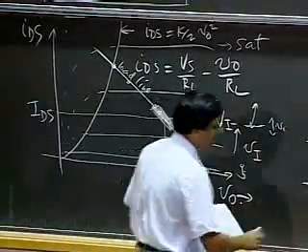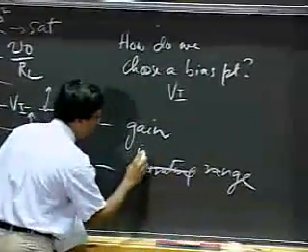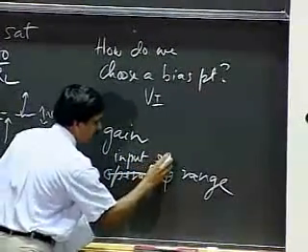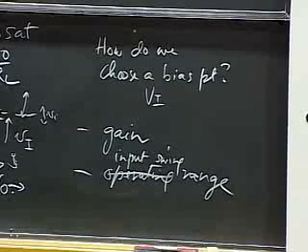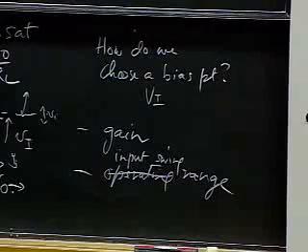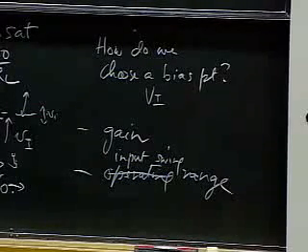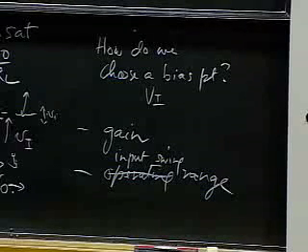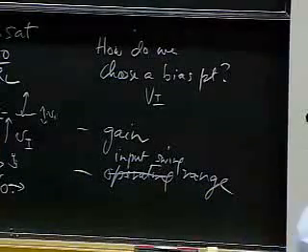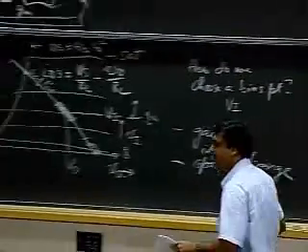I shouldn't call this operating range. I should call it input swing range. We defined the valid input operating range as the range for which the amplifier satisfied the saturation discipline. So the two key issues are the gain and the input swing. All right, so let me show you a quick demo and try to point out on a graph some of the characteristics that relate to the matter we've been talking about so far.